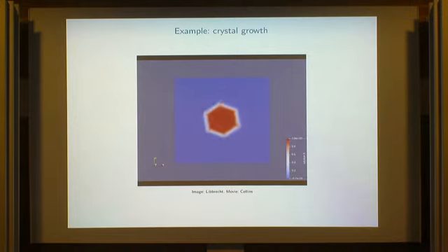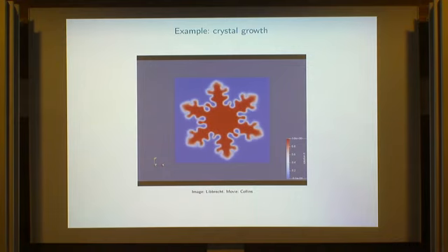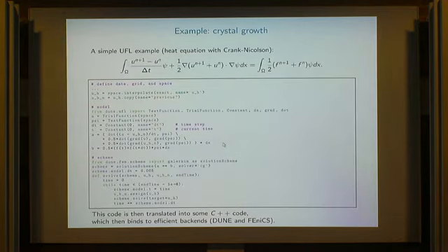Right. What kind of time stepping do you use? It's a fixed one. Yeah, it's a fixed time step. For this one, the default time stepping scheme is just the backward Euler. So you have to solve a nonlinear problem in each time step by default.